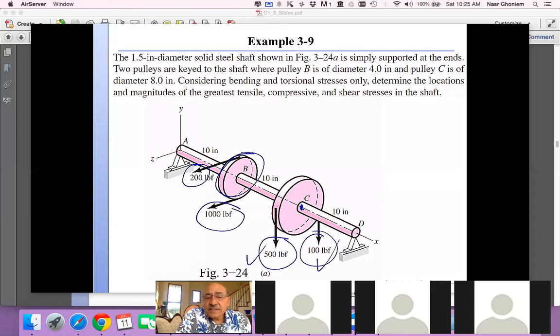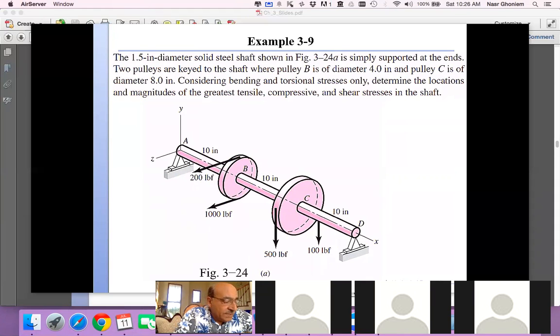If the loose side is not given to us, we can obviously compute it because the torques have to be equal. So this is not necessary to be given, or vice versa. Or they can give you a relationship between these two. So you can play a few games here to utilize the fact that the net torque is equal to 0.